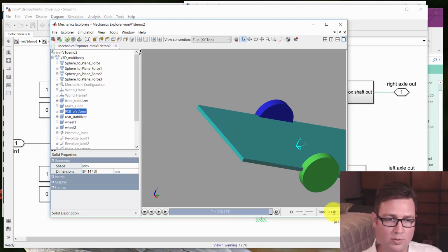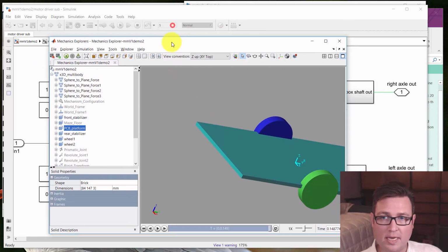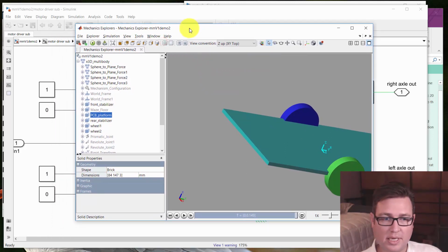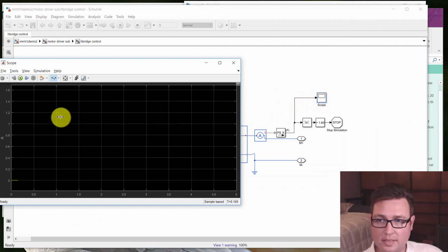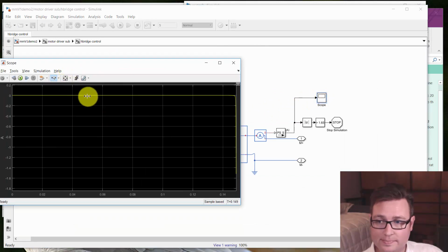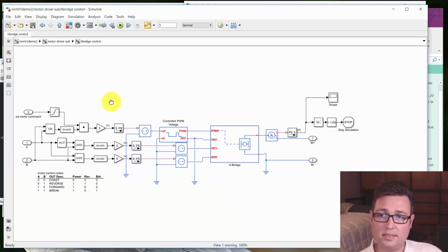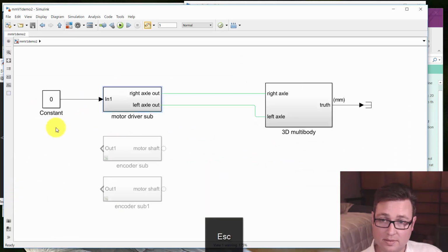And now we stop at 0.14. Remember, we have this set to go 5 seconds, so we're still getting above the target current. And if we go look at that, we can make sure of it. Yeah, we're getting to below negative 1.6 or 1.65 amps. Why is this? Because remember, the motor command is 0. We're driving it with the 0.